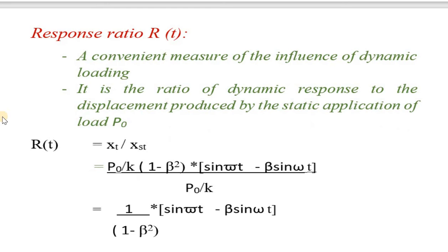Then another term is response ratio. Response ratio is a convenient measure of the influence of dynamic loading. It is the ratio of the dynamic response, the displacement produced, to the static response. So response ratio is this x of t, which we have studied now, divided by x_st.